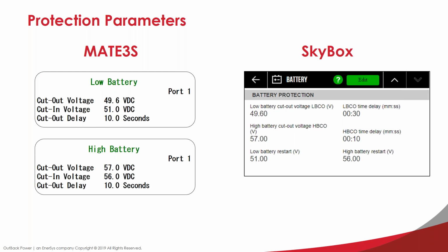I'm not going to go back to it, but if you look on the Simplify sheet, it has an operating voltage window. You want to make sure you're below that. And then cut-in voltage, similar to cut-out voltage, just a volt or two below your high battery. And the same for the delay is, again, personal preference.